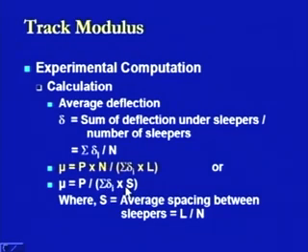the sleepers. And this is another standard condition which is being created, because this spacing of the sleepers is also defined previously as far as the specifications are concerned. Now, as these specifications are known, we know the p value and we know the s value. The only thing which again needs to be measured are the deflections on all the sleepers provided on any of the rail length. So, again only one parameter out of the 3 parameters needs to be experimentally computed, and then we can finally compute mathematically the value of the track modulus.